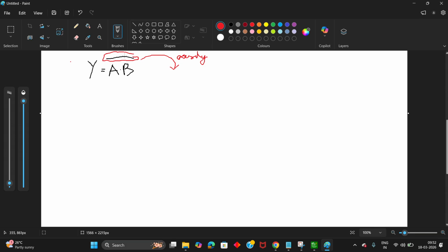You shouldn't care about the whole bar. You need to implement just the internal logic below the whole bar. When you implement the internal logic which is below the whole bar, then automatically you are going to get the output of this NAND gate. Why? Because in CMOS we get the complemented output at the output. Okay, so how to design this circuit?